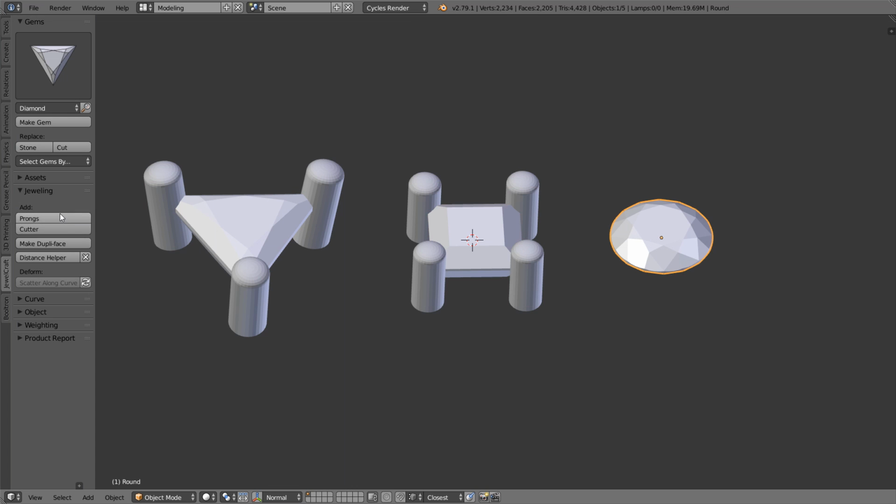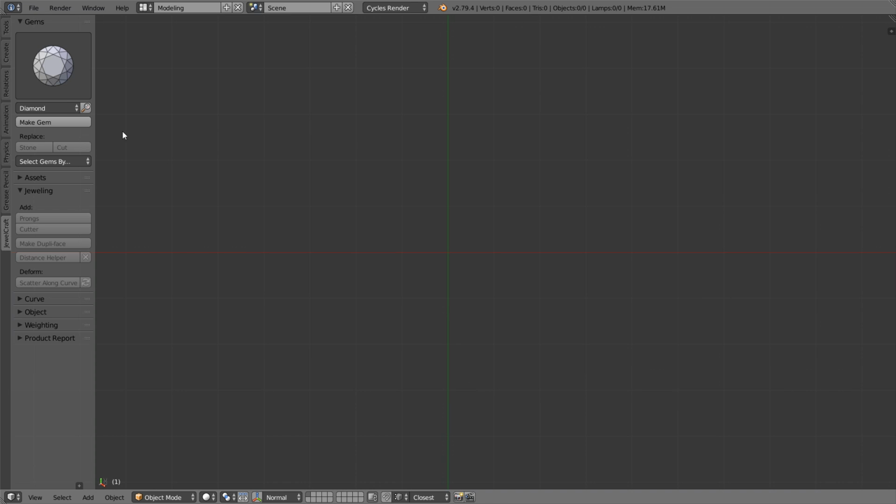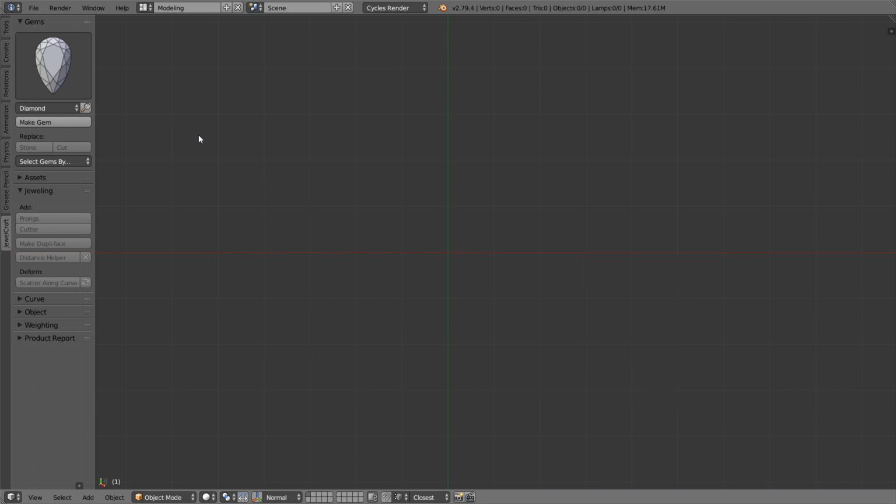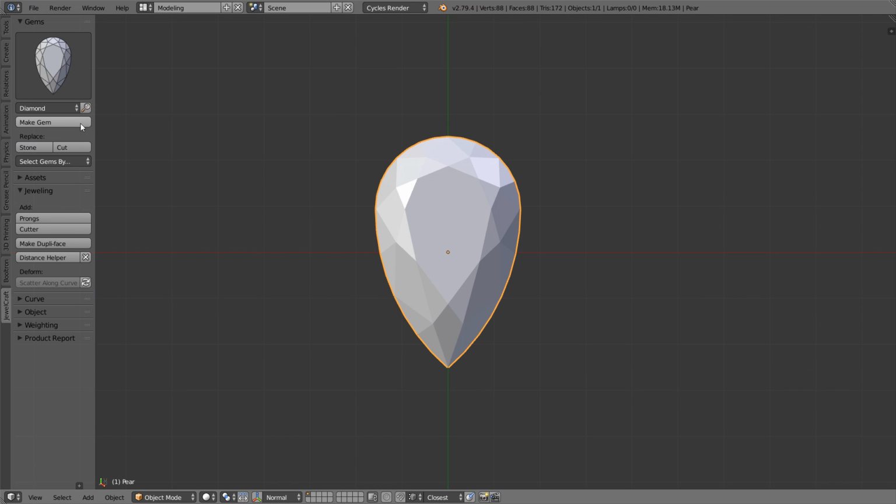The prongs tool was specifically created for round gemstones, but its flexibility allows us to create prongs for the majority of symmetrical gems with no problem. But how does it handle a gem with a more complicated shape, like a heart or pear? And that is what I'm going to demonstrate. We can't create prongs for a pear cut in one go because of its asymmetrical shape. That's why we do it in 3 steps.